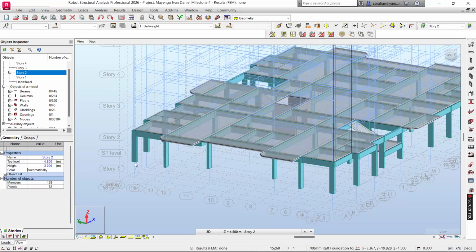Now, if we have pressed the columns at the grid intersection, then that should be the basis to press all other proceeding elements. If I'm to press the next beam, it would run from the grid intersection to another grid intersection where the column is. Unless that column has been moved, then you would run it from that other grid where the column has been moved to. Note you can as well introduce other grids. If, for example, you move the column, you can introduce a new grid at that specific location. We saw that.